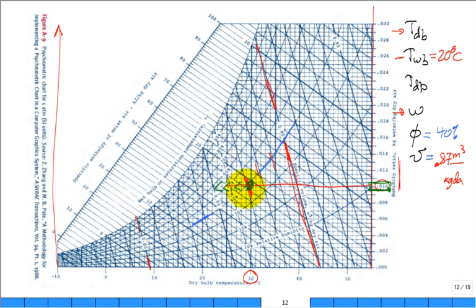But you go from 40% to 50%, 60% relative humidity, and you continue to cool it to 70, 80, 90% until you get to 100% relative humidity. You just draw a straight line over till it hits 100% relative humidity, and then you can read down. What does the temperature look like for the dew point? 13 degrees C. That's right.